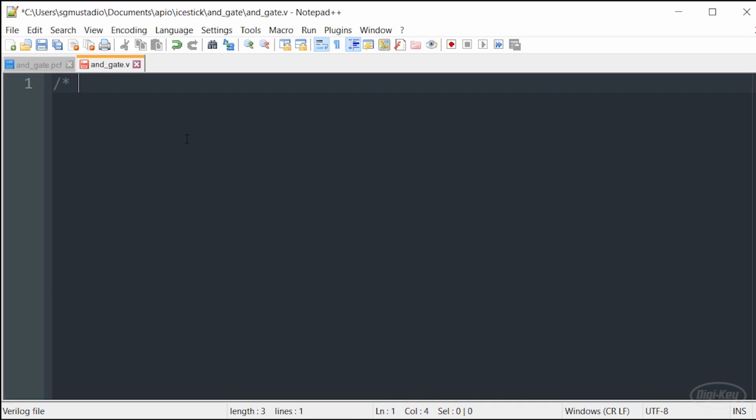The C-style comments work very well here, like this works well for line or inline comments, as well as the // comments. I'm going to define my module here and give it a little comment that says when both buttons are pressed, let's turn on the LED. A module is a keyword in Verilog that says I'm going to create a block of functional code. And remember that this is not procedural code necessarily. It doesn't run one line at a time. This is just a block of functionality that gets implemented as hardware when we run synthesis.